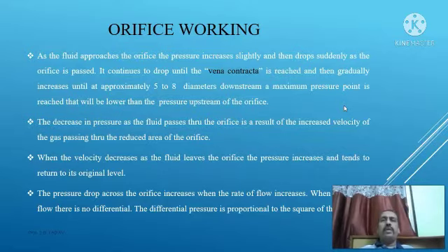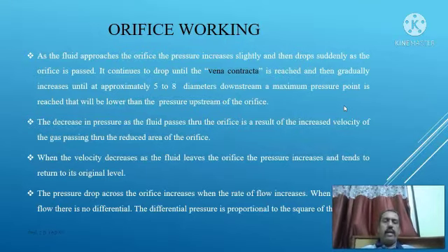The decrease in pressure when fluid passes through the orifice is a result of the increased velocity of the fluid passing through the reduced area of the orifice. When velocity decreases as fluid leaves the orifice, pressure increases and tends to return to its original level. Pressure drop across the orifice increases when the rate of flow increases. When there is no flow, there is no differential. Differential pressure is proportional to the square of the velocity.